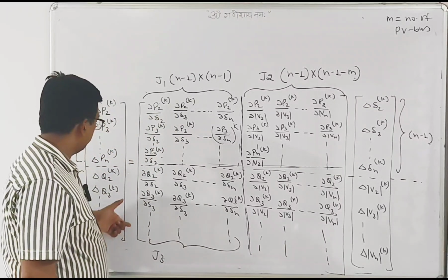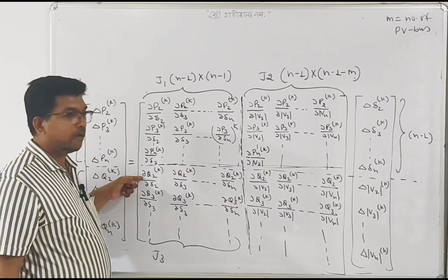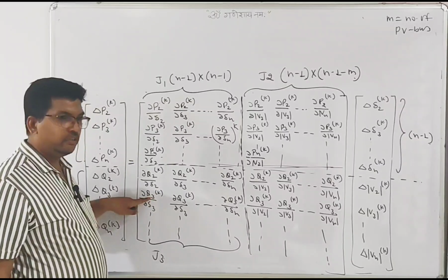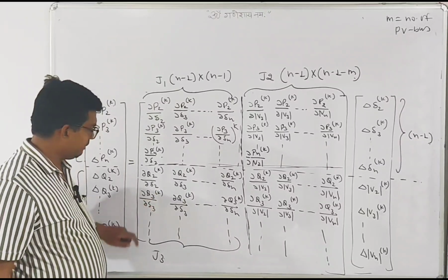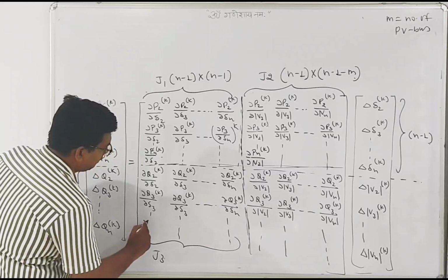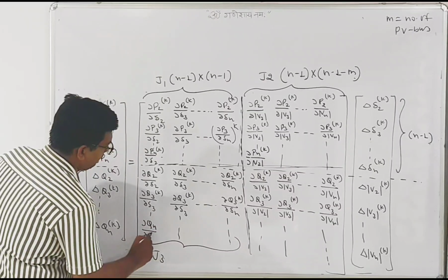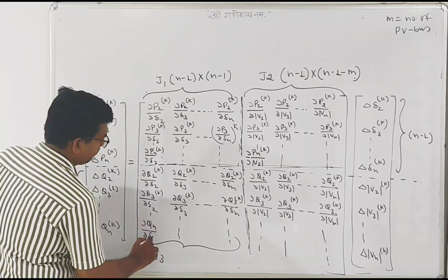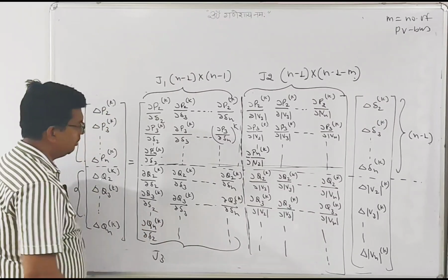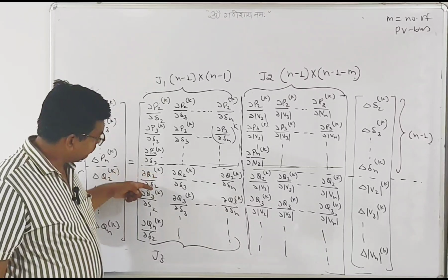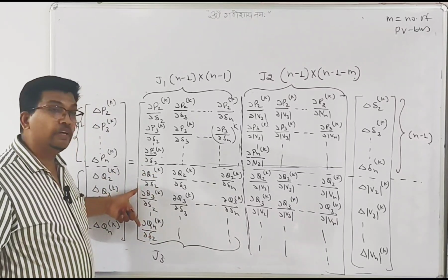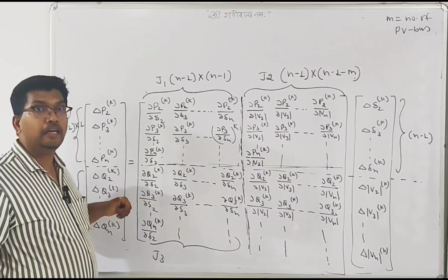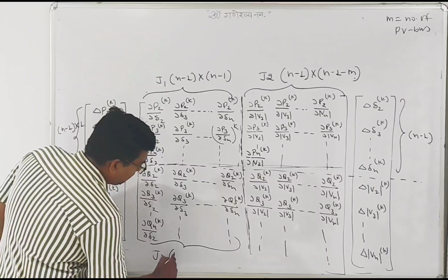Okay. Now these are basically the reactive power terms. There is a partial derivative of the reactive power with respect to delta 2, the partial derivative of the reactive power at bus 3 with respect to delta 3 and so on. What will the last term be? Delta Qn upon delta delta 2 and this becomes K. So how many reactive terms come? Q2, Q3 up to Qn, and we know very well the reactive powers are associated with the PV bus. Okay, so that's why here again, how many rows will there be?